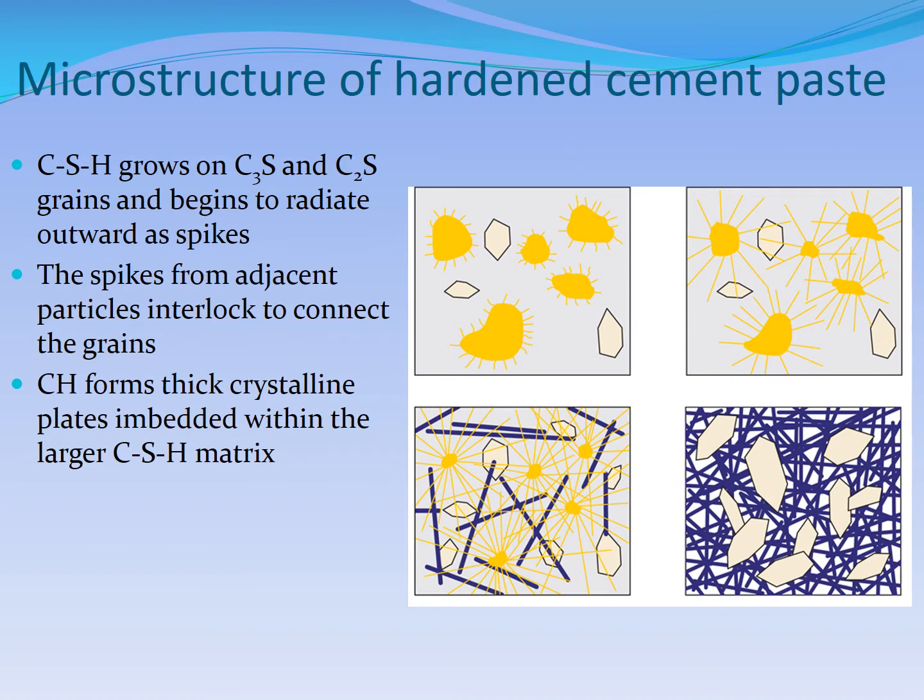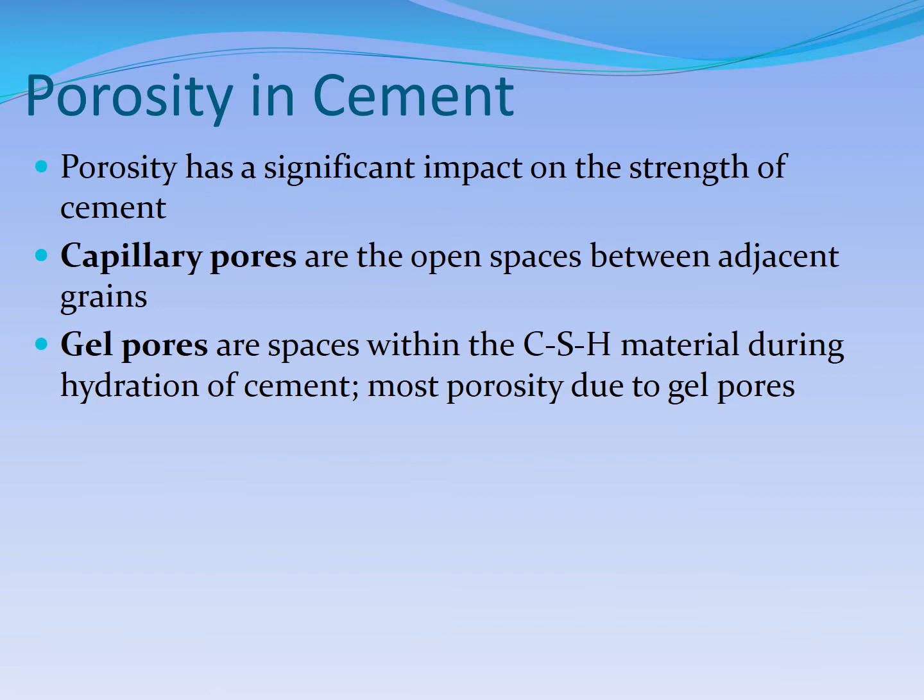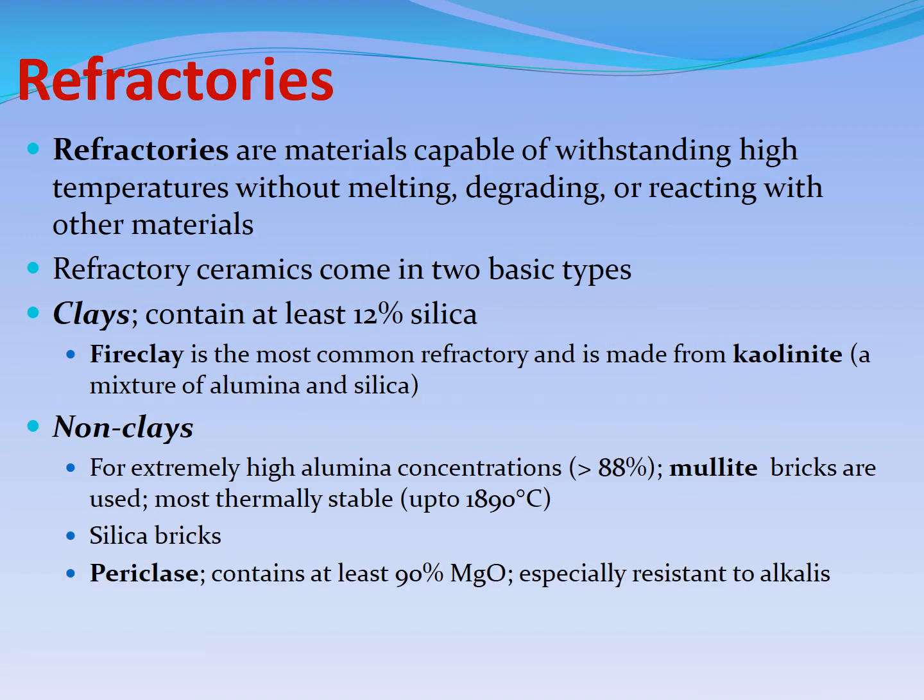So we can see some of this structure here. Partly crystalline, partly non-crystalline, a mix. Porosity in cement. You see, there are capillary pores and then there are gel pores. So porosity is there, it can breathe. That is why once they make concrete also, then you do curing of concrete, right? You pour water on it and you let it cool, and then pour water on it, let it cool and dry. So some porosity, if it is there, then it is good or bad depending on your requirements. So that was about cements in general.